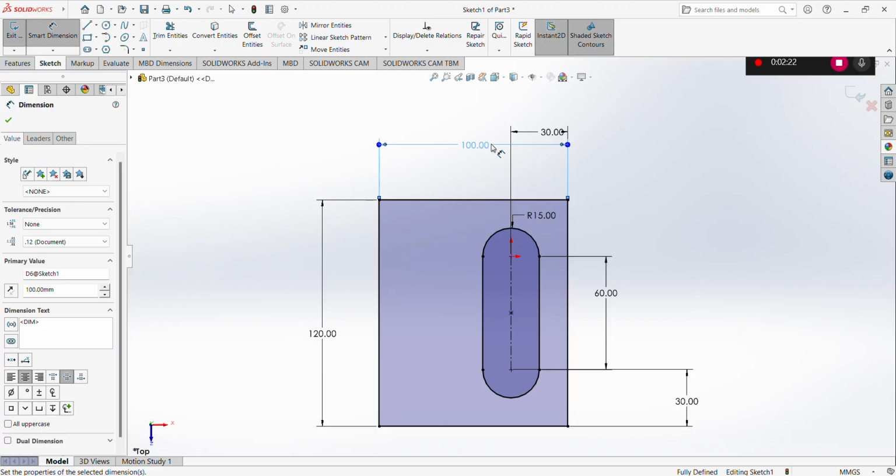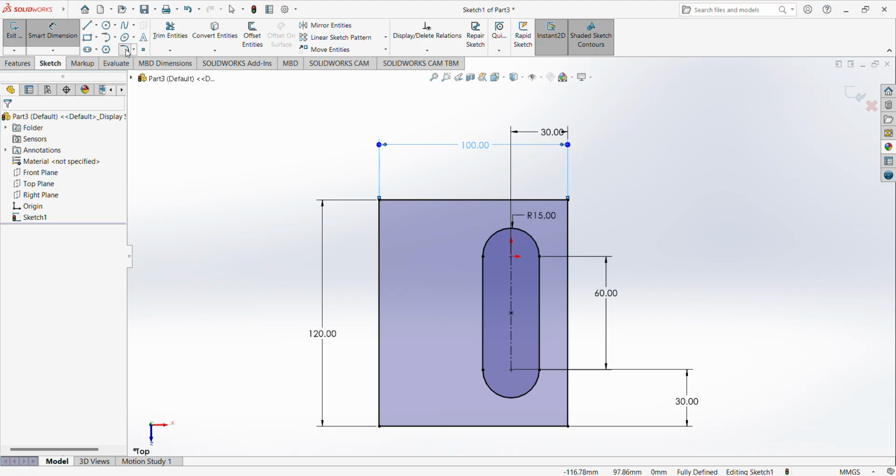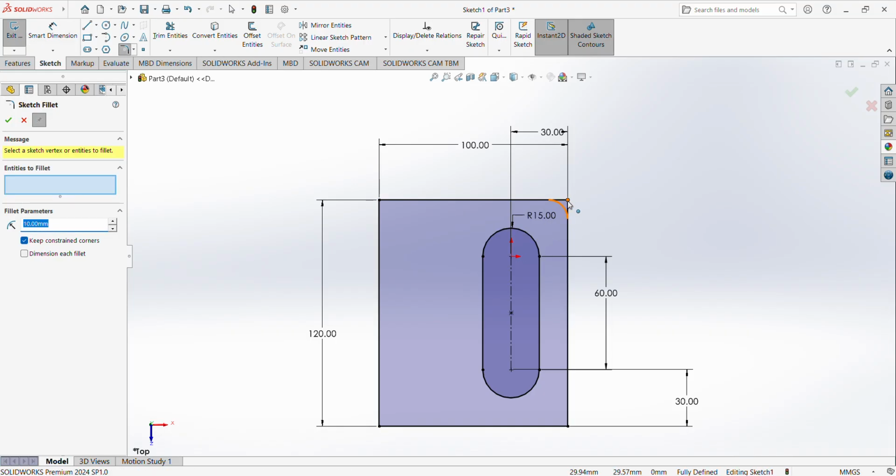You can either extrude this, then use a chamfer to chamfer it, or you just use a circle. Because we are dealing with a plane shape, I prefer we just use a circle, or you can still use chamfer. If you look at this space here, there's a chamfer tool here, chamfer and fillet. Because this is an arc, we'll use the fillet to sketch fillet. Once we do this point and this other point, and their radiuses are 30, you just change your dimension here to 30. So this is it. Then just say yes.